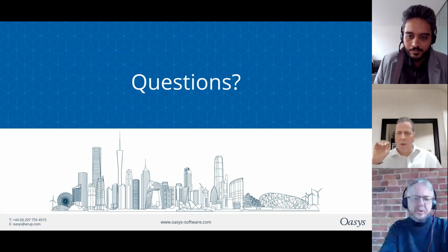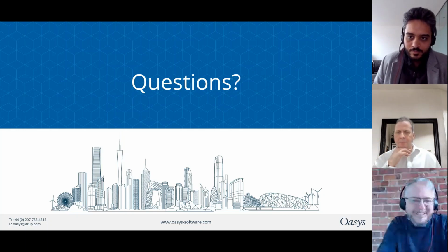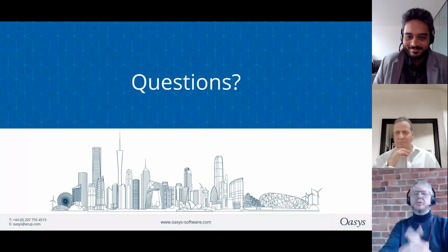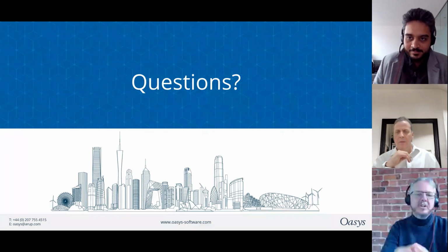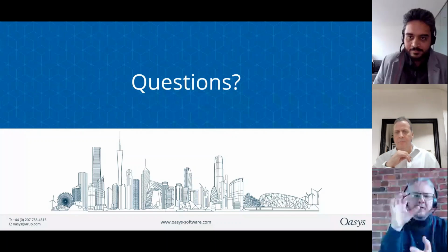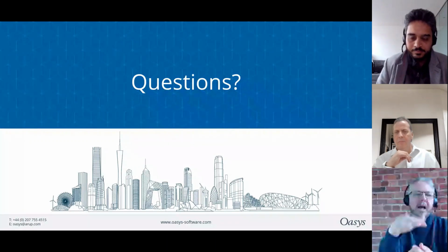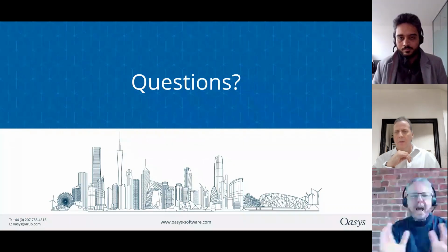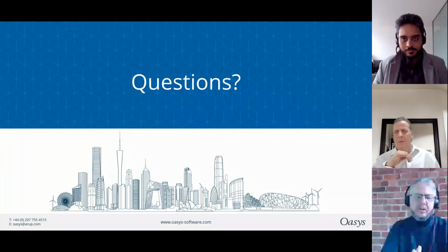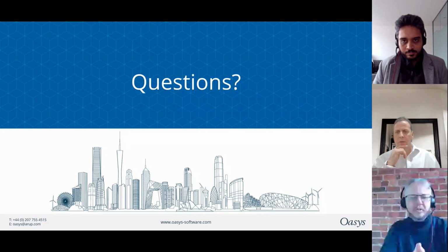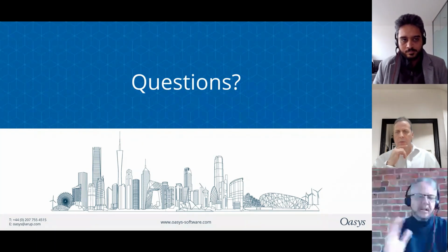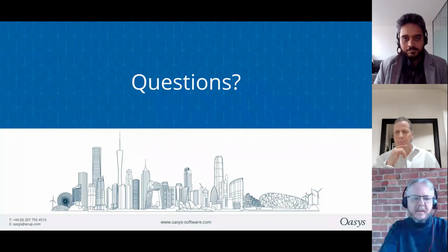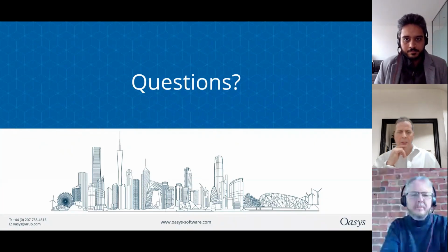Yeah, okay. And of course you've also got the stage analysis, so you can analyze the stress state of the existing structure, and then add on the new structure, so you can then see how that changes between the two. So you can look at construction sequencing, but also adding on and refurbishment, adding and removing loads to existing structures. So yes, that is all capable in GSA.